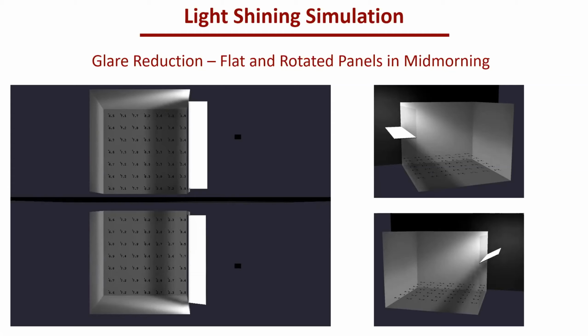That is an object that actually no longer needs to be there. I was initially modeling with just light fixtures while I was figuring out how to model sunlight more correctly. Those fixtures have been disabled, but I had forgotten to remove them from the model. This black line between the two spaces is just a tall wall I created because both of these were running simultaneously, and I didn't want light from either one somehow affecting the other.